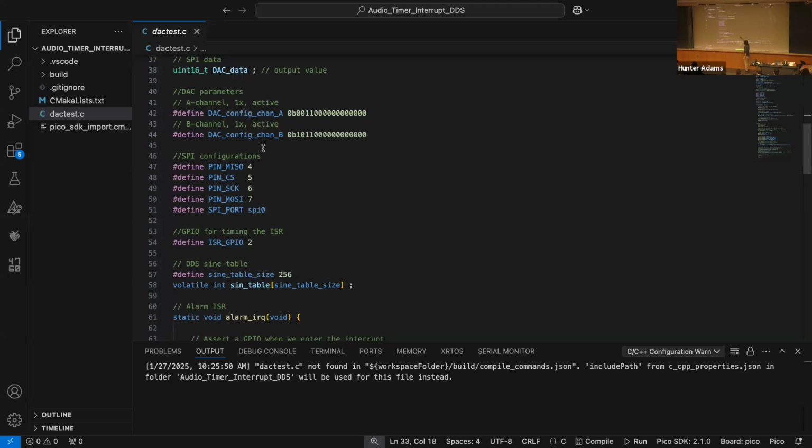The uint16_t there makes our program, again, it's not of tremendous relevance for this class because we're all using the same hardware, but it makes it a little bit more platform independent. The word short, in our case, on our devices, means 16 bits. If you were to go to a 64-bit processor, short might mean 32 bits. But uint16_t means unsigned 16-bit integer on any platform. So you'll see uint16_t, uint32_t, uint8_t. And like I said, for us, we could alternatively use char, short, int, and they mean 8, 16, 32 bits.